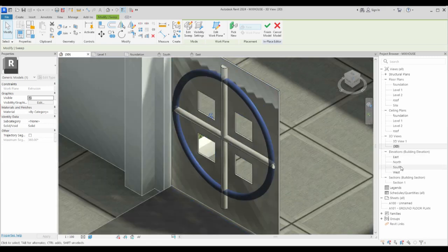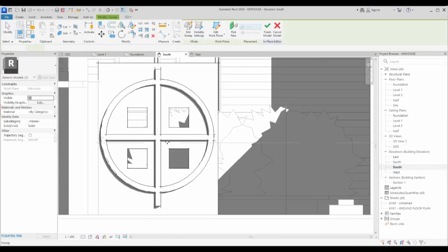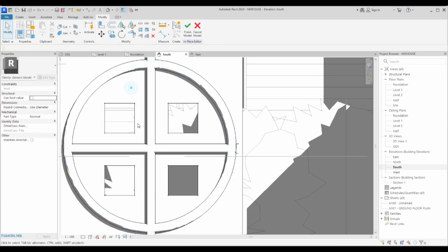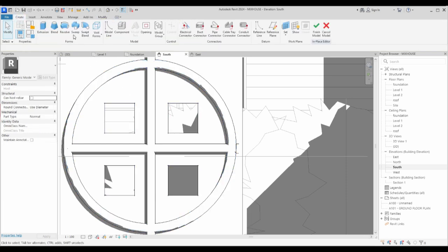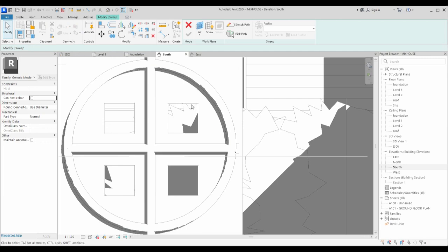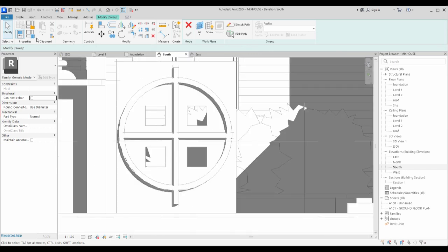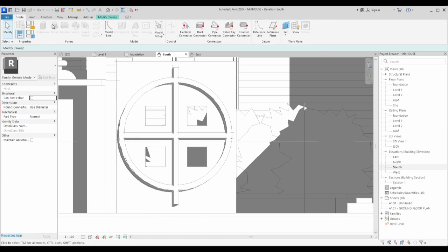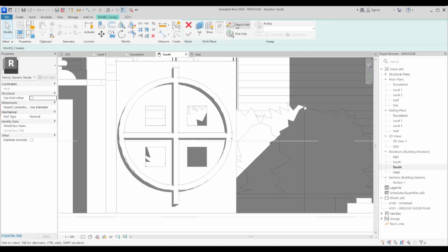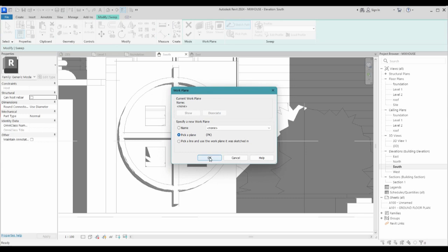Now what we need to do is go to the start elevation. So here we need to design something special again. Create this one and use the same sweep to do whatsoever you want to do. So if you ask me how I do the void, it's just that when you are in this sketch mode, you are not going to leave. You just go to create, and at the same time click on void, and everything will come back for you. So placing sweep,